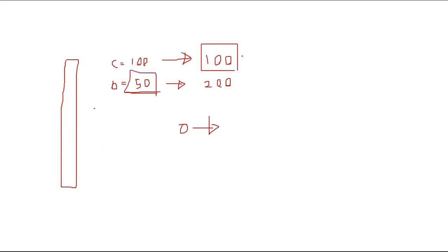You have to understand which comes first. Under this phenomenon only, you will work out buckling, where it is less than the yielding, that means the compressive strength of the material.